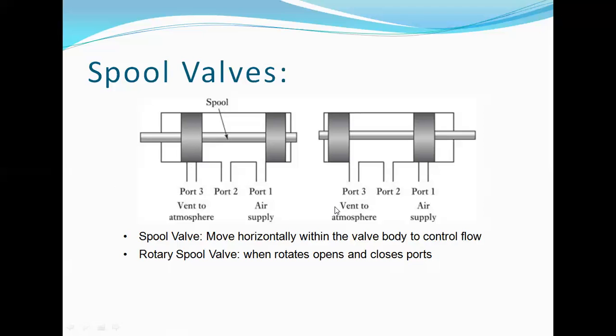And this is the condition of the second one: port 1 is in closed condition when the spool is completely in the extreme left position. So the already entered fluid will not move towards port 1, and the gas always tends to move towards the open space, that is, the high volume, which is directly connected to the atmosphere, and hence it is released to the atmosphere.